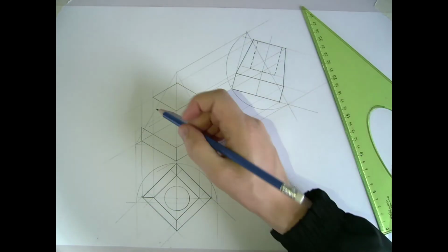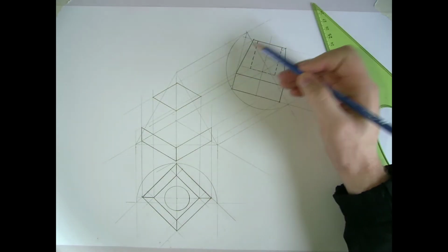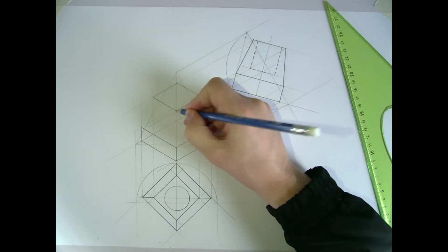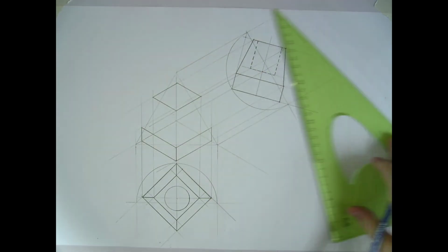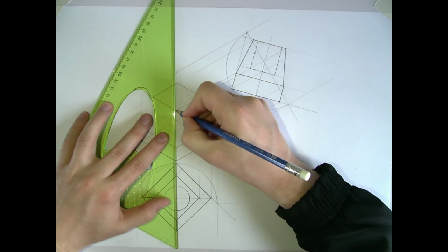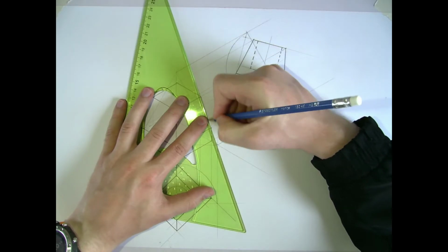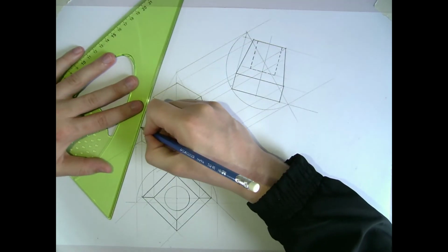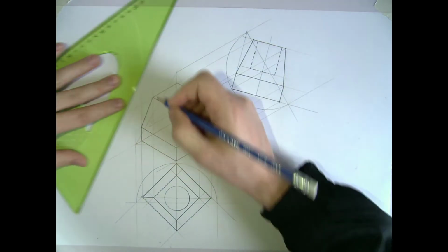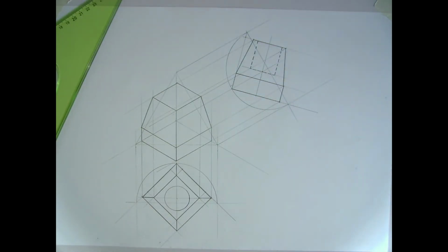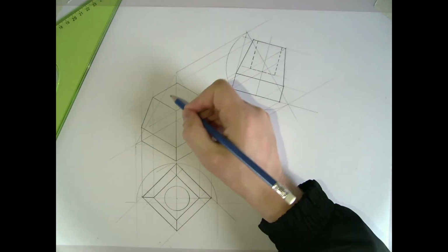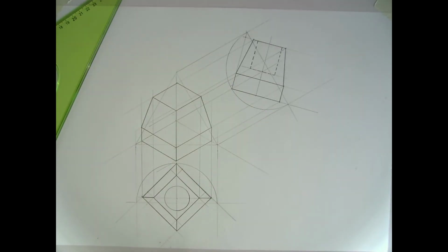Now, for each of this, we can see in our 3D that there's lines sloping down. Those lines join from each point down to the lower corresponding point. So that's this one going vertical here and here. Now that completes part C, draw the axonometric projection of the body of the candle holder. So that draws the entire block part of it without the cylindrical hole up on top.